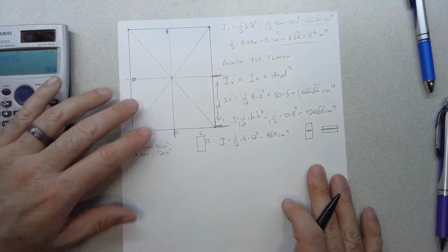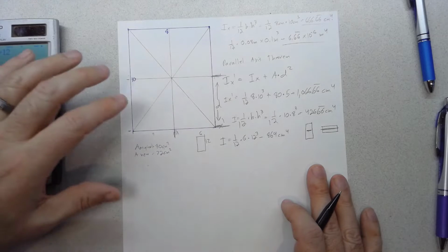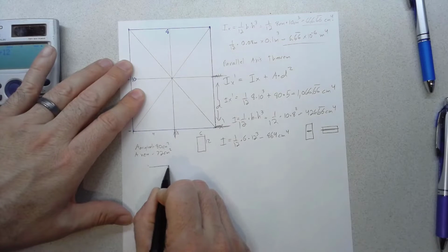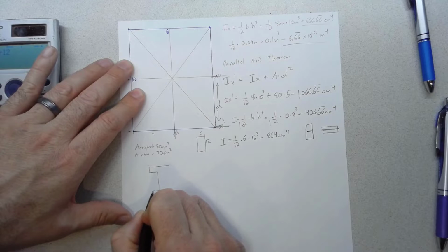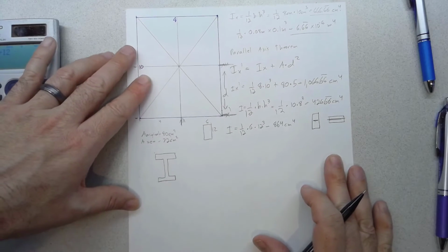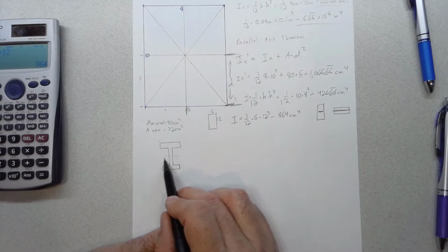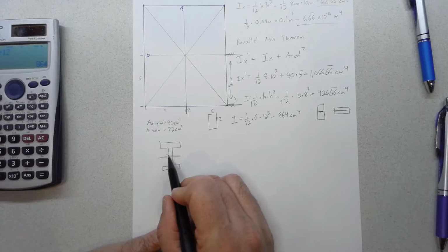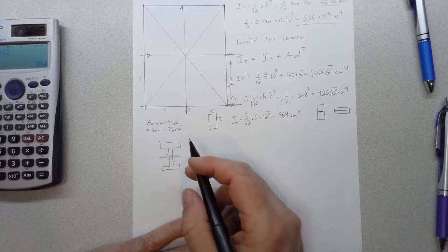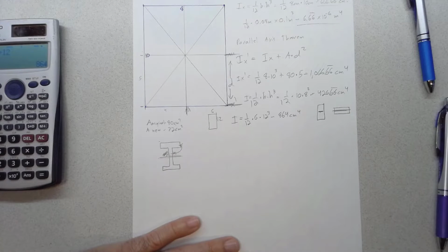So then as we got into materials in engineering where we were actually able to tailor the shape of it, so if you think of that as steel beams, or even in wood construction, when they started getting into wood I-joists or web joists, the shape of the beam is typically something like that, where we're trying to use the material most efficiently so we get as much of the material as far away from the axis that we're bending about as possible. Because material that's down here close to the axis doesn't do us any good. So by cutting out some of this stuff in here and moving it up here, we can make the beam stronger for the same amount of material. And that's what a lot of engineering is, finding the most efficient way to do something.